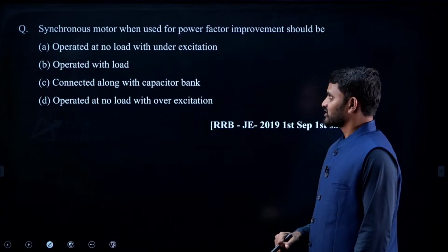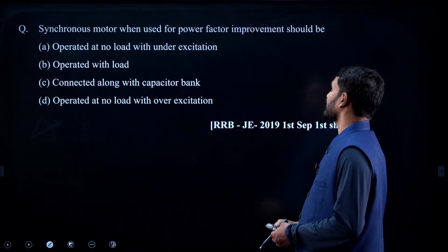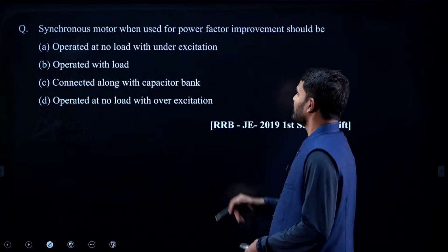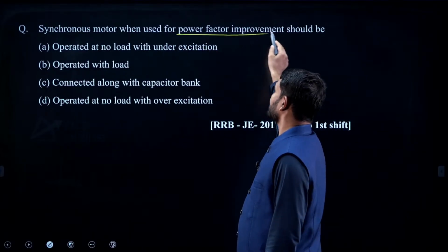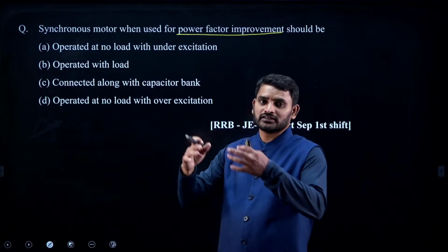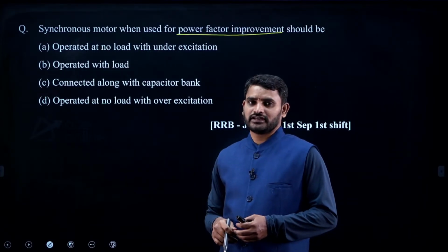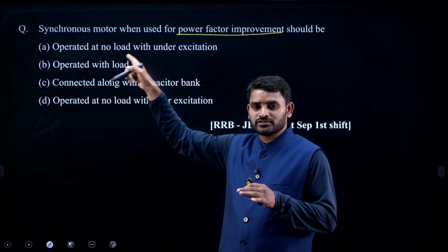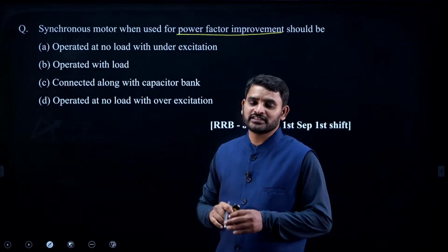Look at this one. Synchronous motor when used for power factor improvement should be... So an overexcited synchronous motor is going to deliver the reactive power, right? For power factor improvement, we will use the synchronous motor as a synchronous condenser.